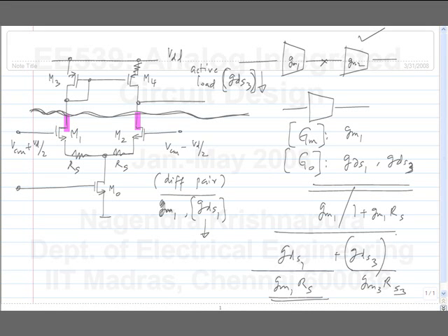It will increase the output impedance, but also it will reduce the transconductance. What I would like to do is to keep the transconductance the same, but reduce the output conductance. That's what I do when I increase the length and width. So I have the same bias current, I increase width and length, let's say by a factor of 2. Then I have increased the value of output resistance, but I have kept GM the same, assuming the square law model.